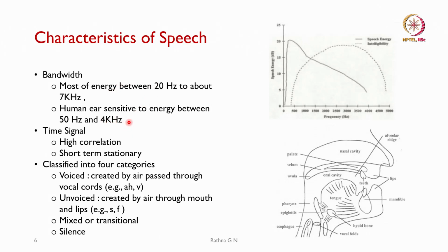For all mobile communications now, we know that the bandwidth to be covered is in this range, so we will go with wideband speech, which is 16 kilohertz. You can see the auditory range given by this curve. So, narrowband and wideband will be used based on this.